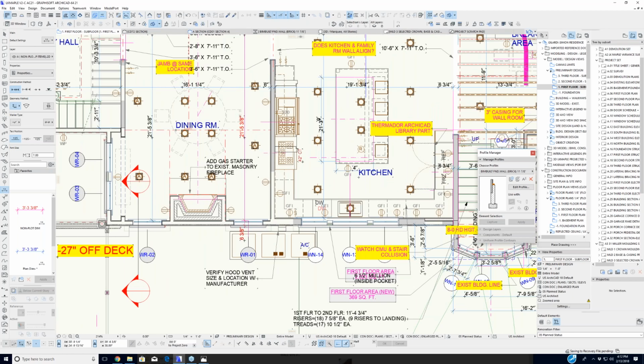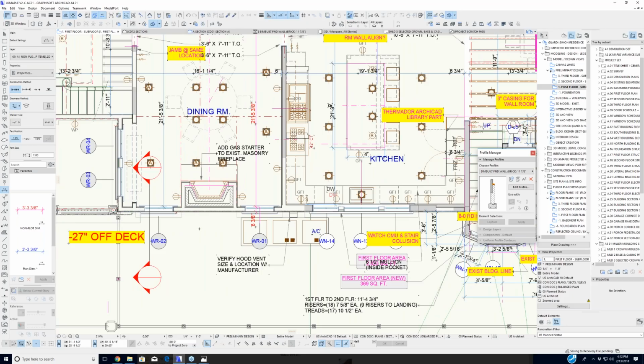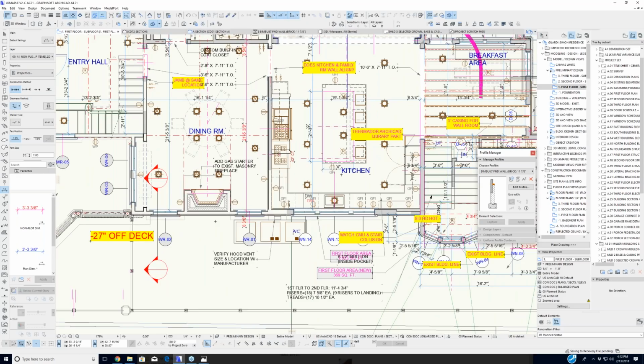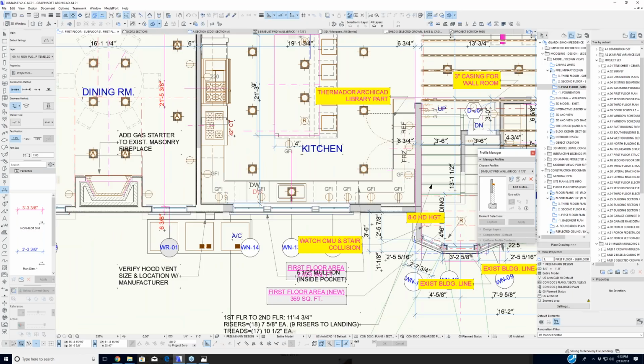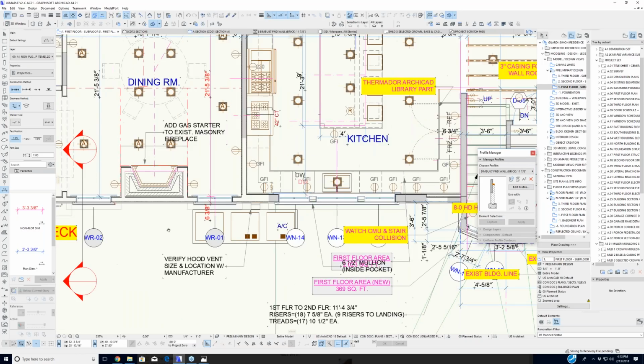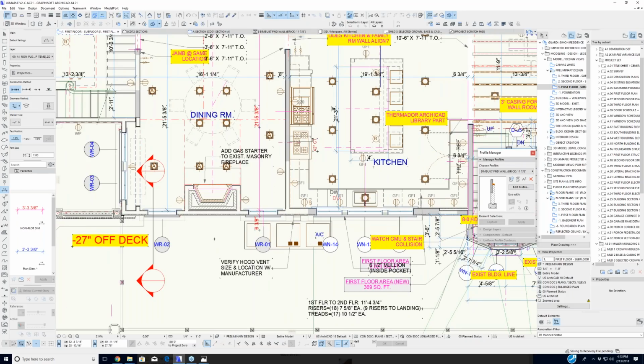And then you can use a morph on the outside that's the thickness of siding, and you might open up that entire elevation and put one big material, 5/8 inches thick, with this new material right on the wall. Now the limit on that is, if they said let's put another window in here, you'd have to go back in and create a hole in that morph. So that does create some problems. That certainly comes up. So you're using what's there and working around whatever limitations there are.